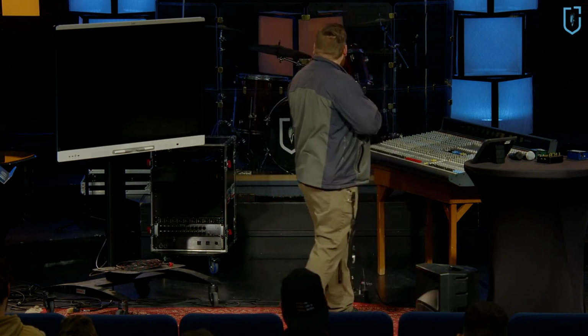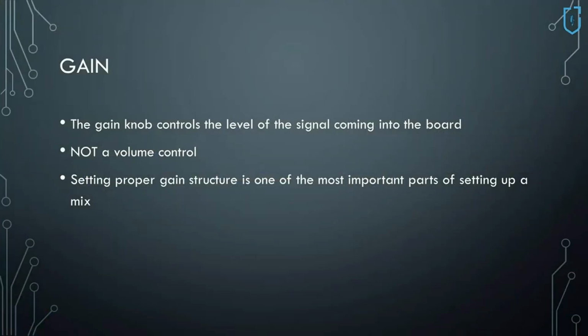Gain, this is the big one, not a volume control. It does affect volume, but it's not a volume control. It controls the level of the signal coming into the board. Setting proper gain structure is one of the most important parts of your mix, in my opinion.